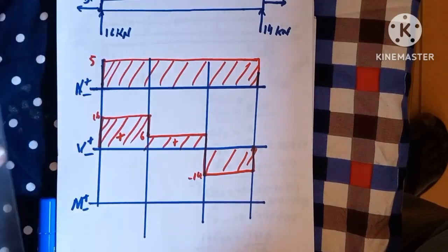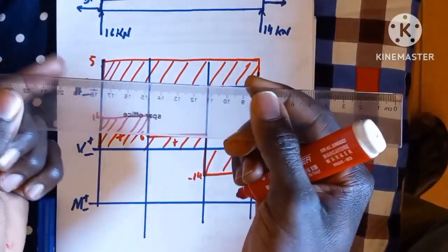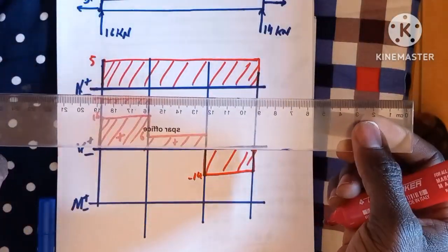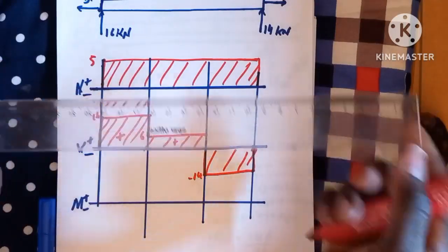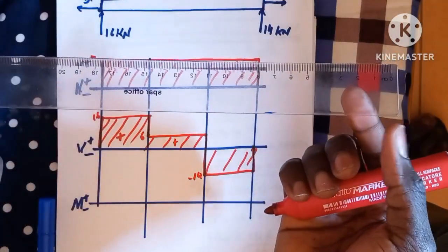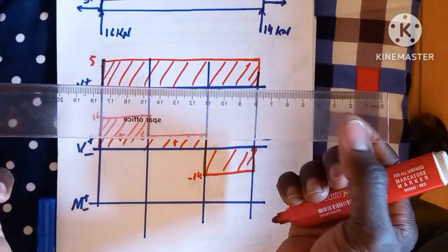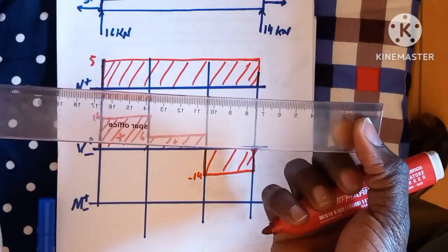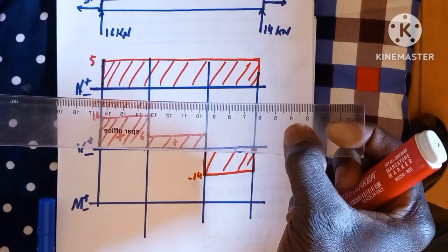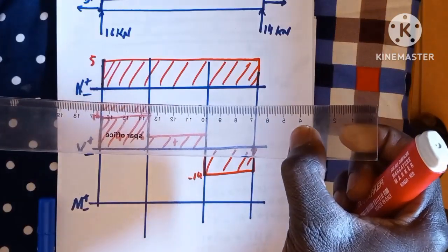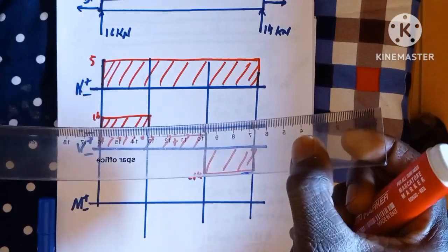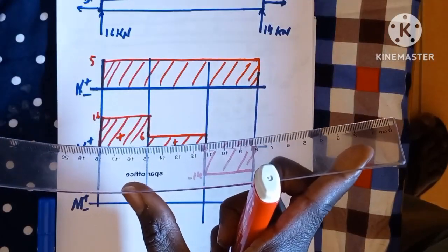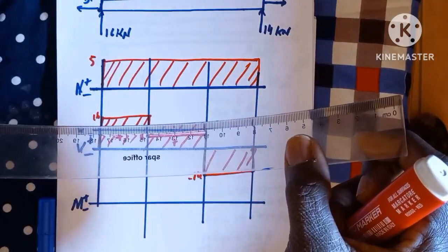Let's say, for instance, you have this ruler, and there's a force acting on this beam from the top, and your hand is like this, right? So if there's a force acting on this beam, it will tend to push it down, while your hand under this ruler is also trying to resist that, right? So it's going to cause a sagging moment, right? So the dangerous cross section here is going to be what? The global minimum. Now there will be a minimum here, right? So that's the reason your graph is going to be going down this way.